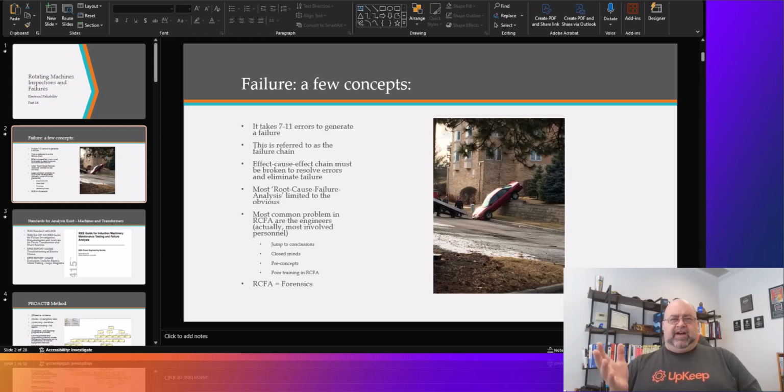Well, then why do we have the 5 why concept of root cause failure analysis? Those are usually meant for very simple applications that haven't had a significant impact. But if I have a high dollar impact, or one that's considered serious for whatever reason, is important to somebody in the organization, then I need to do a more robust analysis. Why? Because sometimes there's not just one root cause. Sometimes there's a culmination of causes that lead up to one.